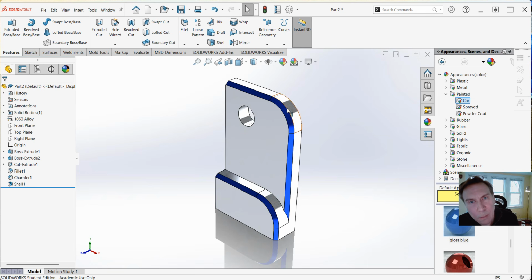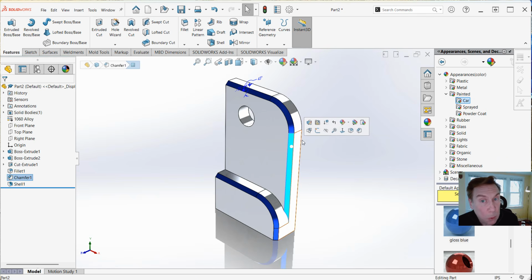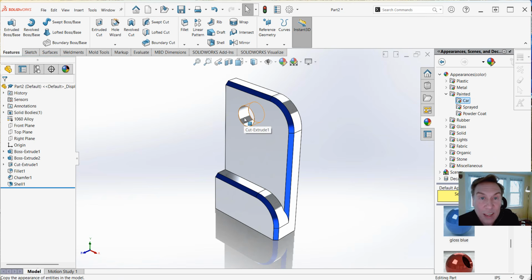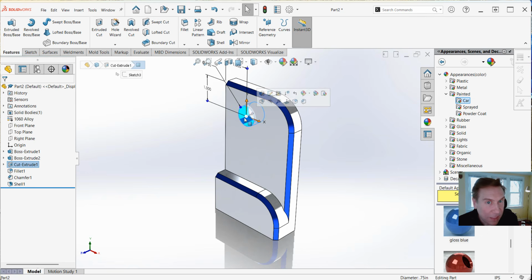Now let's say we wanted to copy that color and you didn't want to have to find it in here again. Click on that surface of the blue. Go to, right here, the dual beach balls. Go to copy appearance. Now select the surface. Now remember, the surface indicates the little square. Click on that surface and go to paste, which is the clipboard.